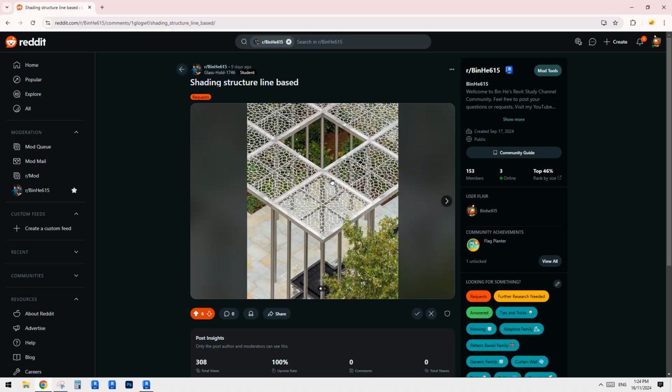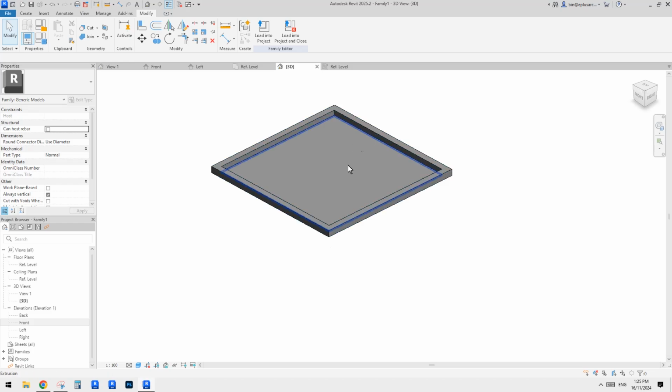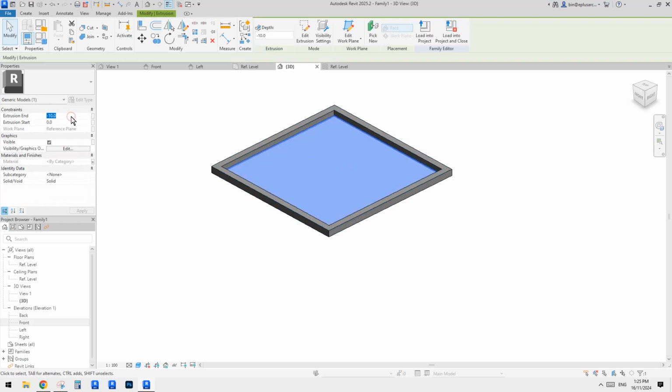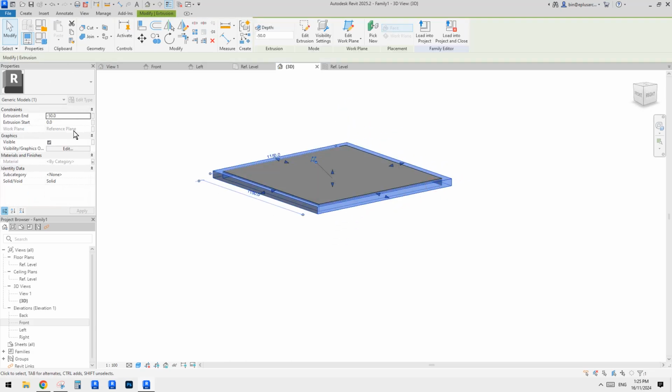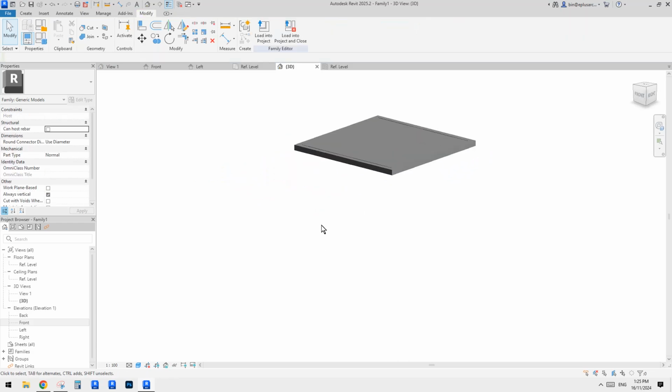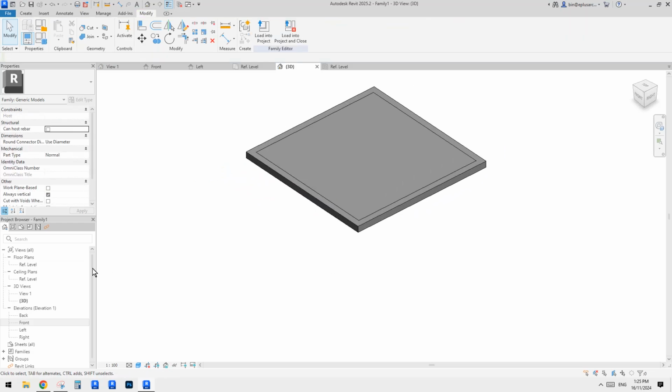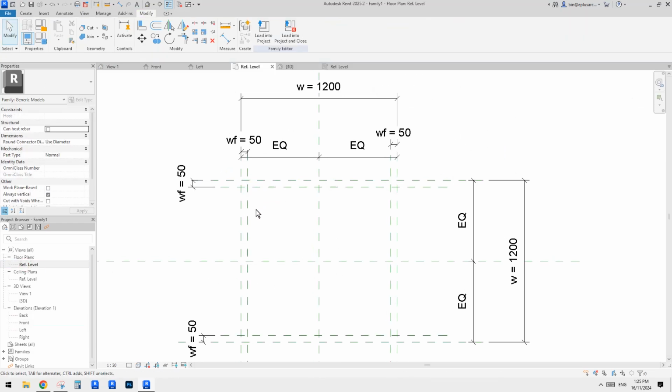If you want this one to be along with the top of that frame, we can quite easily just type negative 50 and then negative 40. So the thickness is still 10, right? It will align with this one because we have this negative 50 there. And then we can just add some columns.